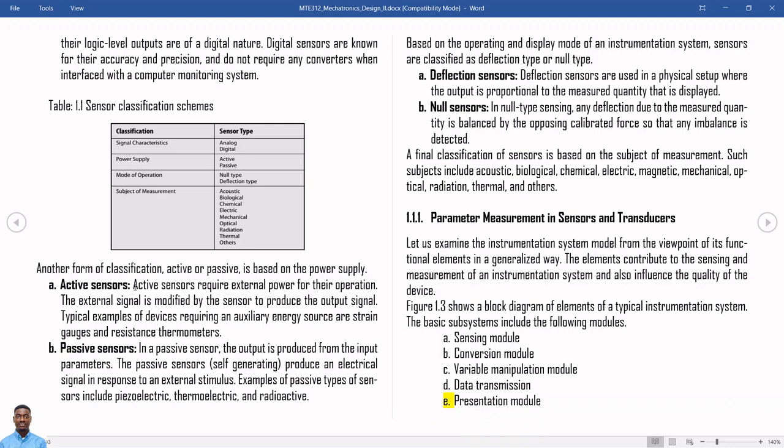Or your IR sensor, infrared sensor in this case. Those kinds of sensors emit energy. Your ultrasonic sensor sends a signal when it is powered. When that signal strikes a surface, it is reflected back to the ultrasonic sensor. So it's that reflection that the ultrasonic sensor measures to determine the distance between itself and the object that reflected that signal back to it.